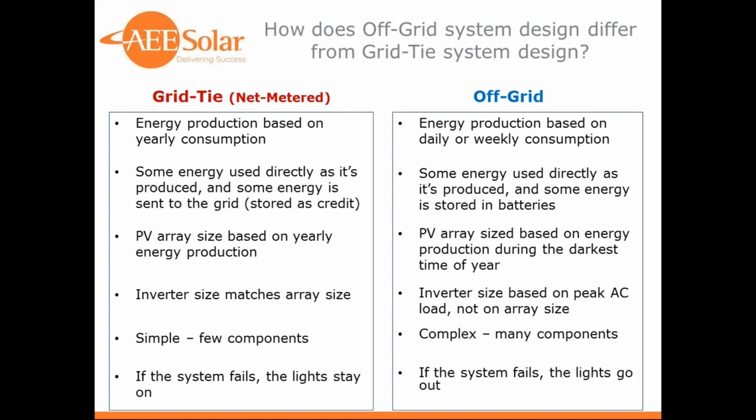In an off-grid system, the energy production is based on daily or weekly consumption. We can't produce energy in the summer and store it long enough to use in the winter in most cases. So we have to look at more pinpoint production, and that affects our system design and sizing.